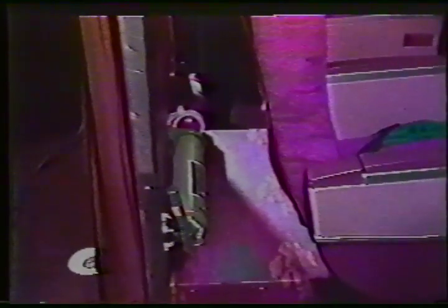R4A has the single Aviox bottle, 5 spare life vests in the side compartment, and crew vest and demo equipment under the seat. L4A is exactly the same. Above the L4 seat, in the last overhead compartment, is a megaphone and first aid kit. On the bulkhead behind the last row of seats in this section, there are 2 more extinguishers, the CO2 on the left and H2O on the right.